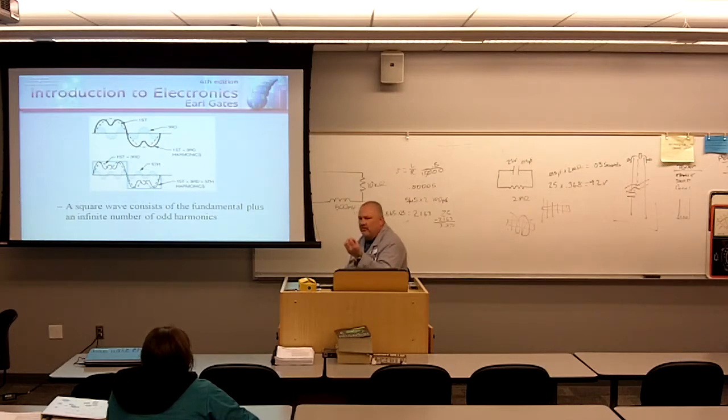If I get my fifth harmonic and add it, my fifth harmonic now is going to be this blue waveform. If I add that to my first and third harmonic, now I'm going to get this waveform. If I get my seventh, my ninth, what eventually is going to happen is this is going to clean up and this is going to look like a square wave.